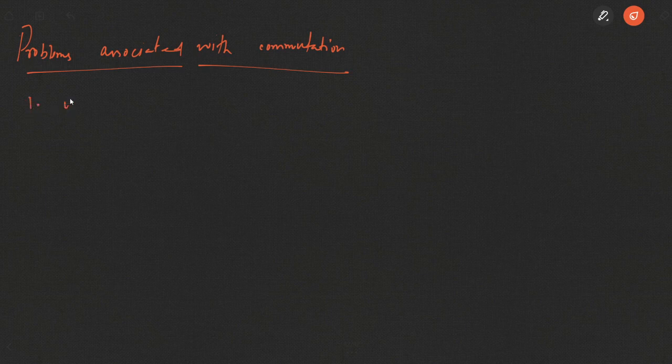There are actually two main problems. One is known as the armature reaction, and the second will be the L di by dt voltages problem. Fine. So we have to discuss two important problems and how to mitigate these issues. The first one is the armature reaction.